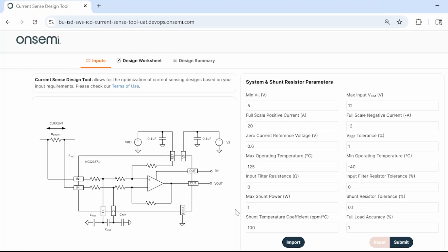And that really depends on your power requirements. If you can allow higher power loss, our tool can often recommend a higher shunt resistance within your budget to help optimize the cost. If you need low power loss, then the recommended shunt will probably be a higher cost but lower resistance technology to reduce power consumption.